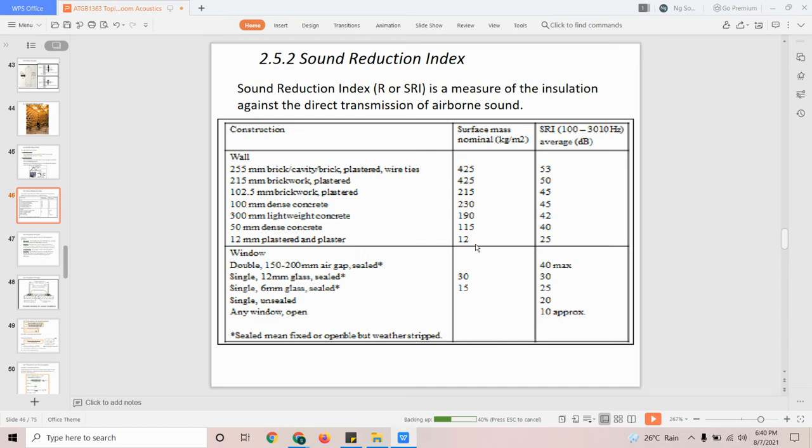So this is done on basic construction material which we use all around the world. So it's beneficial to know how we build a wall, and according to requirement, if it's a very noisy environment, then we should build a thicker configuration to ensure that the quality of life for the resident or anyone who buys the house, let's say if you're living next to a highway, it's not very bad.